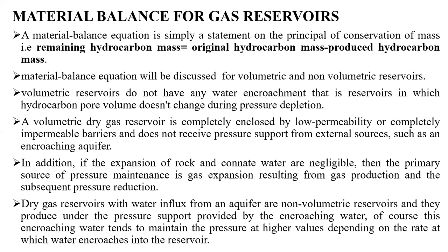As the pressure of the reservoir is dropping, the pressure on the fluid is also dropping and the fluid is expanding. So what is happening at the end of the day is that within the reservoir, the same volume that was occupied by whatsoever before the drawdown will be occupied by a different quantity. It's not as if the volume is going anywhere. That volume is going to be occupied by something else. So if I am drawing, for example, gas out of a reservoir, the remaining gas inside the reservoir expands and occupies the same space that the original amount of gas was occupying.